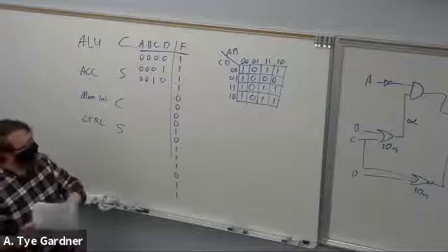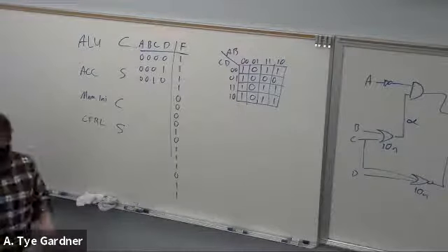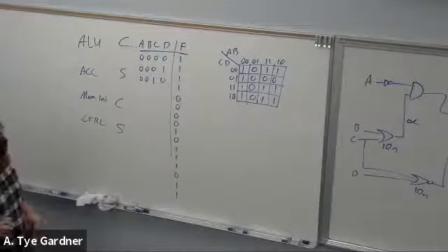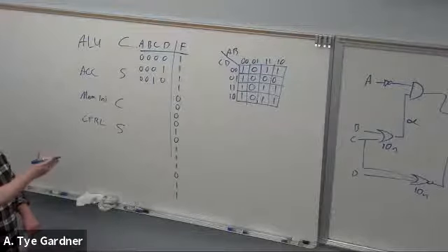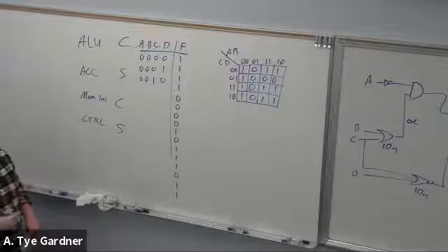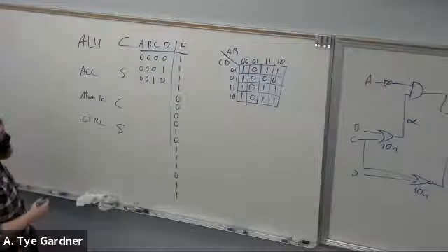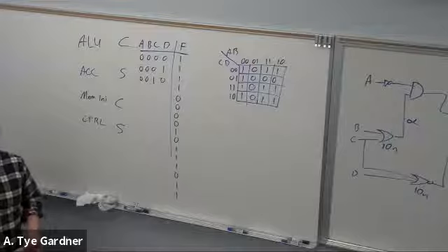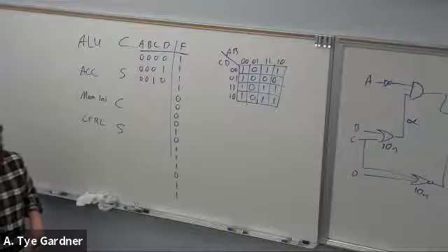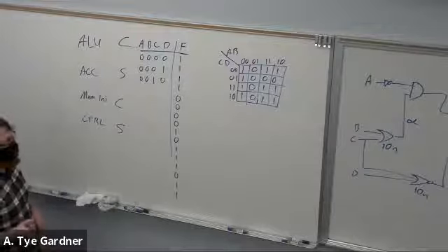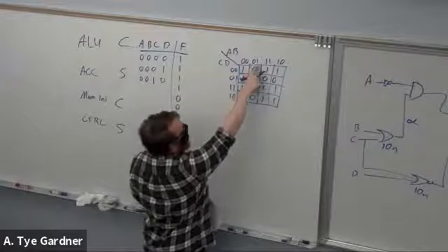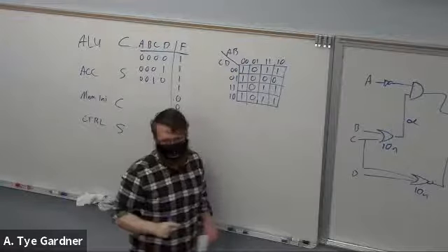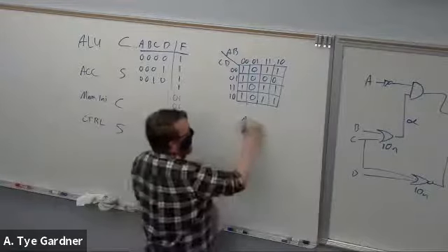There's one other K-map question here too, but I don't think I'll do two for you guys. The other question I get asked is to do a product of sums. It's just the zeros and you flip the inputs. Remember that part, because a lot of people forget that. So this is not A, B, it's A, not B. And it's A.